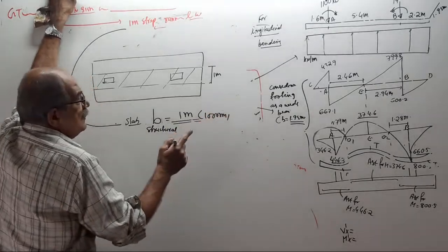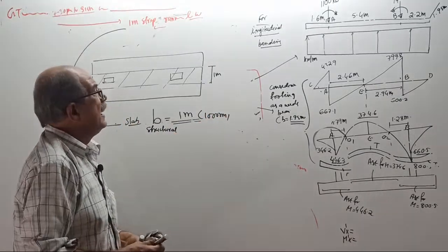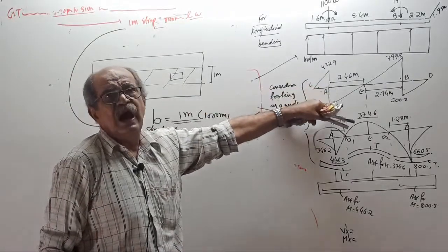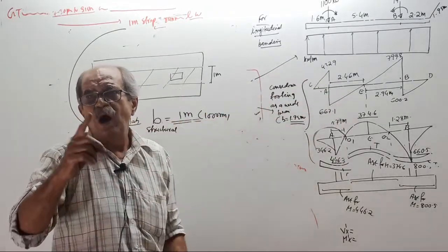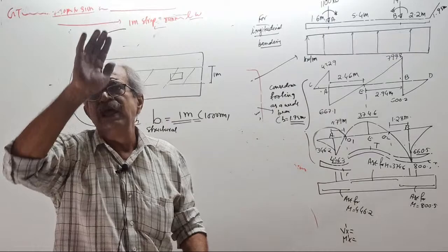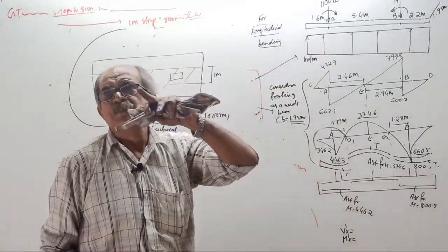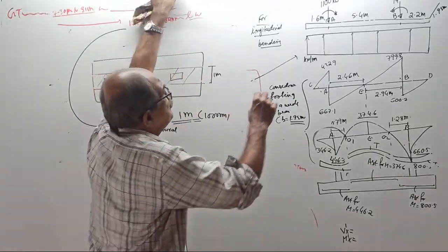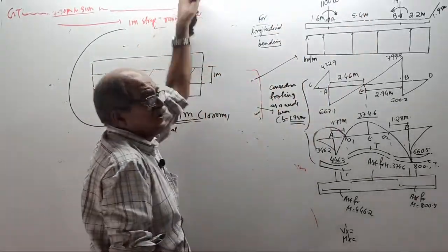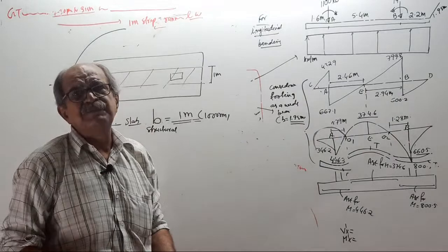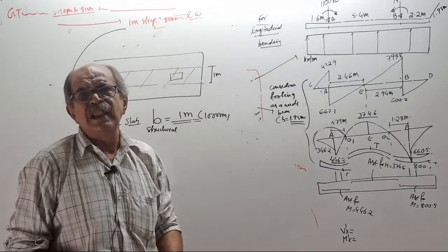Over. Now, one more thing you have to write. Remember, those values, when you consider here, you divide by 1.95. So from the 1.95 strip, it will come to a meter strip. But because of the severe effect under columns, increase by 25%. Some people may say 50%.